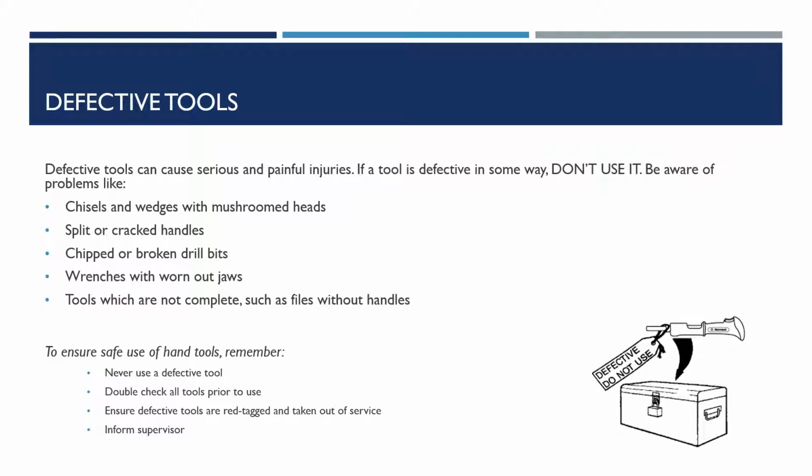To ensure safe use of hand tools, remember, never use a defective tool. Double check all tools prior to use. Ensure defective tools are red tagged and taken out of service, and inform your supervisor.